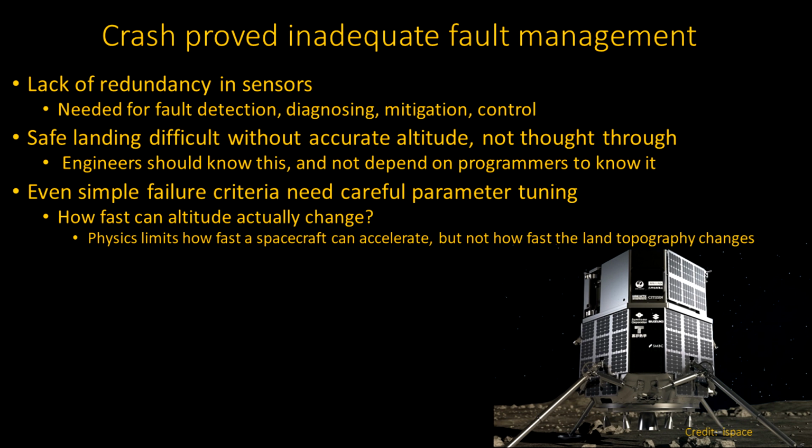They failed in fault mitigation because they didn't realize that inertial navigation would drift too much and could not correct for a huge error in altitude caused by not accounting for the crater depth. They couldn't do that unless they had the altimeter measurement. The control system, adjusting thrust to land softly, was really doomed.